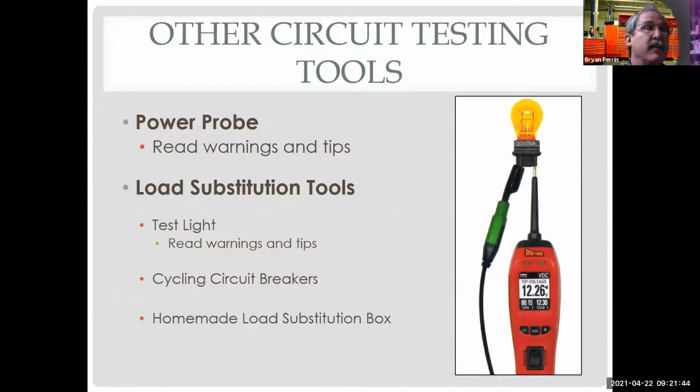I shouldn't say it. The early one, I have some Power Probe 2s, and the connectors weren't as big. So I used my first one so much, I melted the connector that connects to the longer lead. So I bought another one and just hardwired that one. So I still use it. That became my home Power Probe. And then I bought another one where now I got 60 feet of jumper wire. So I can really check a long trailer.